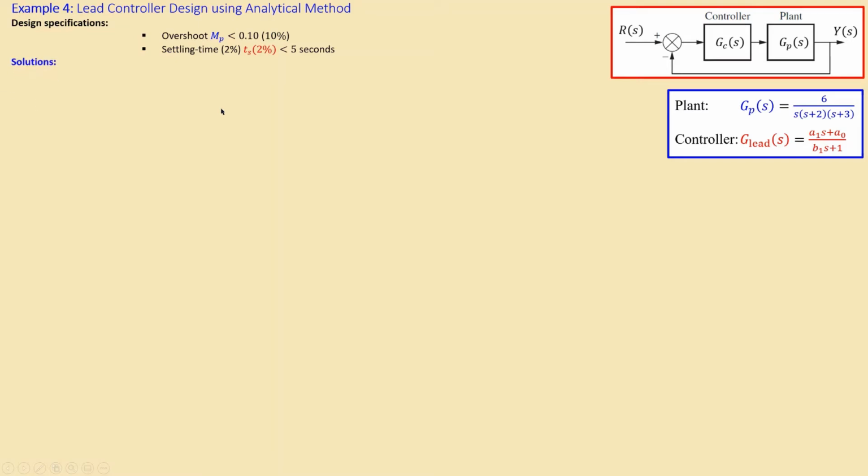I take the overshoot at the edge, 10%, and I can now use the formula for the damping ratio and substitute the value of the overshoot as a scalar. So 0.10 in here and 0.10 in there. If you do the math here, you will get very close to 0.6, or 0.591 to be a little more accurate.